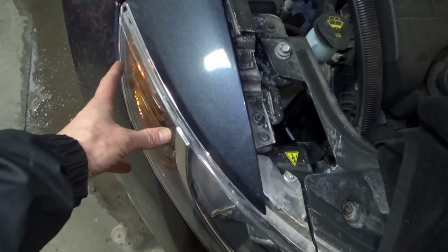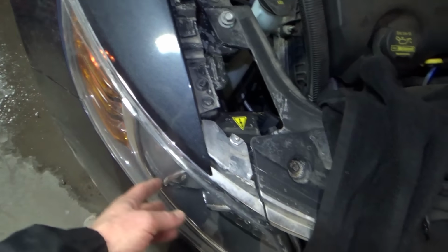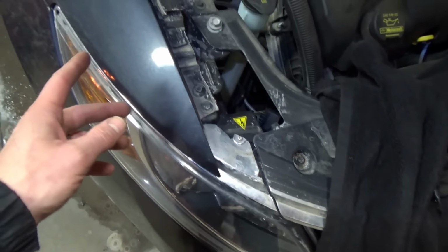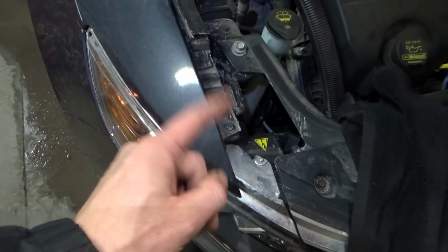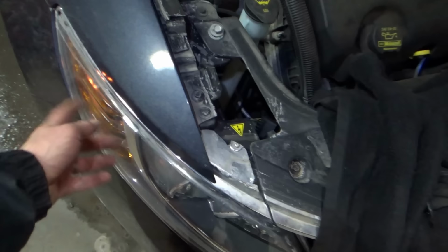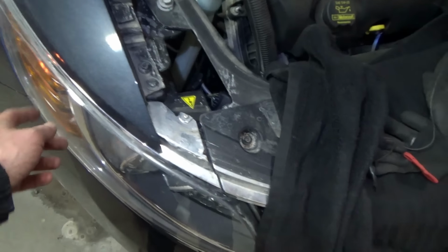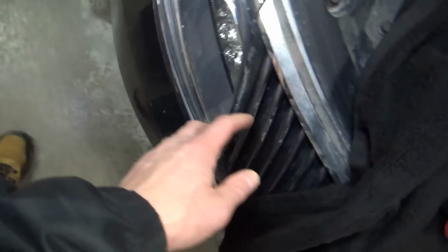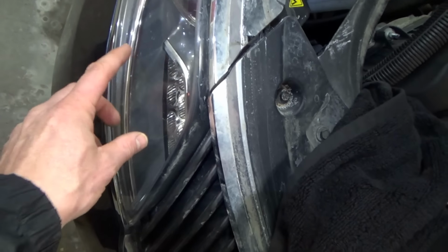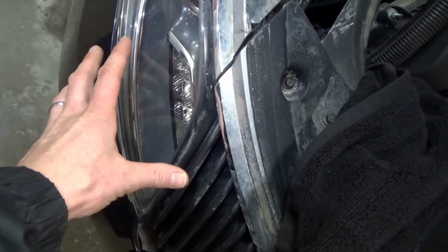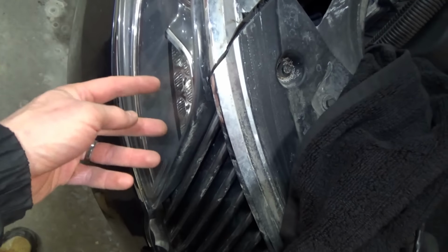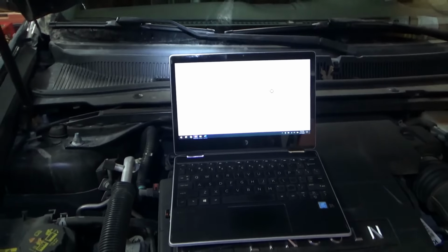Parking lights on, it just stays illuminated. So there's some more fancy circuitry in here that ties the turn signal pulsed command to the parking light, at least this corner one. The one in the center, it's dim with the parking lights on and just gets brighter when the turn signal is on. So there must be two separate LEDs in there. So the diagram is simplified. That's not what's going on.